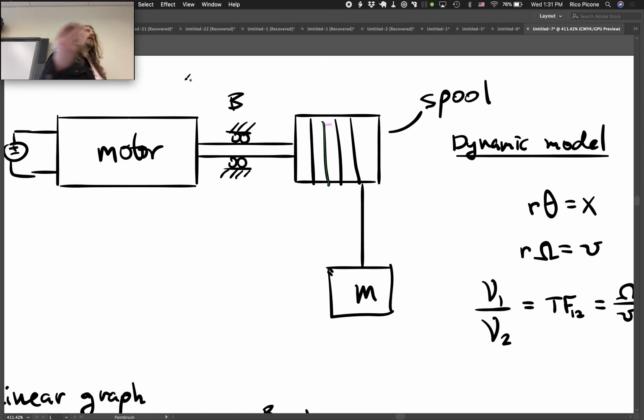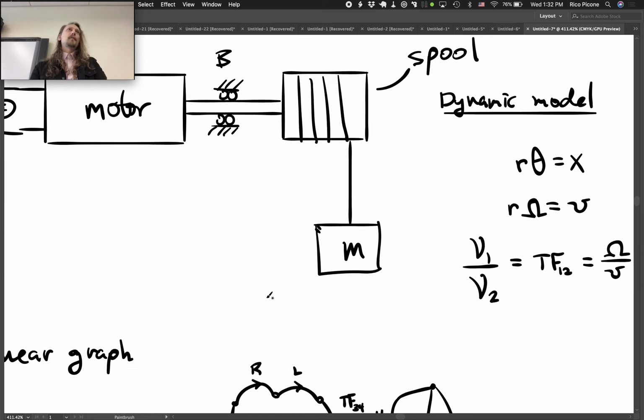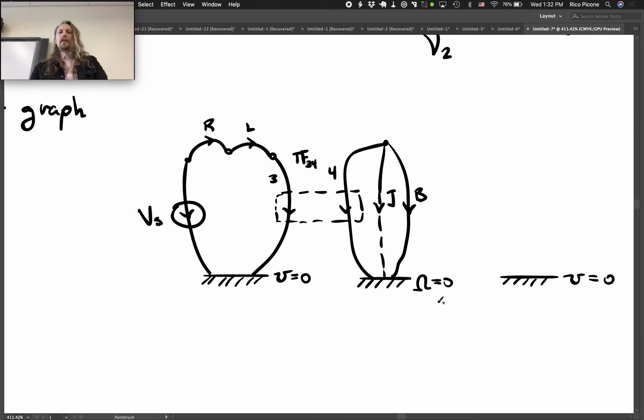Let's say they all combine to have 1 bearing damping B. We could draw multiple and combine them, but let's say we've done that previously and we've got it down to 1 damping coefficient. That's also very practical because oftentimes we find this through measurement. So you take into account all the bearing damping in one parameter because often you have to measure it anyways. Okay, so we've got B.